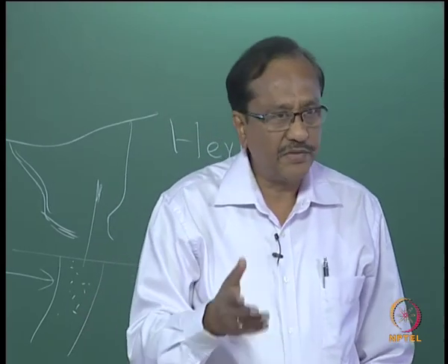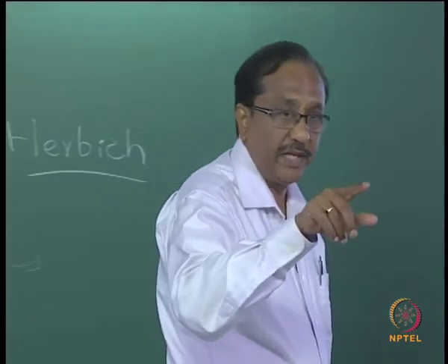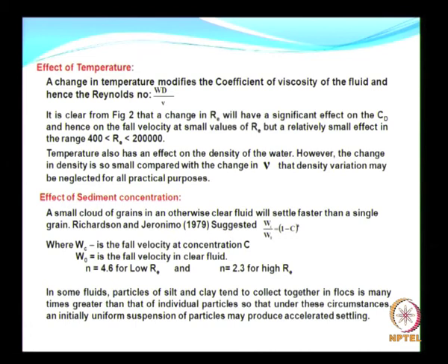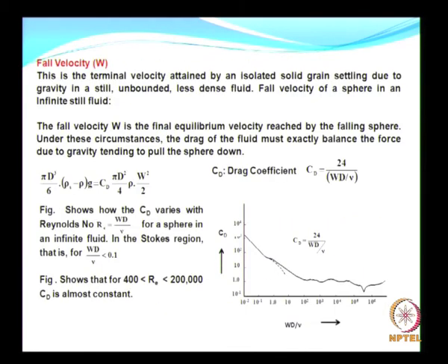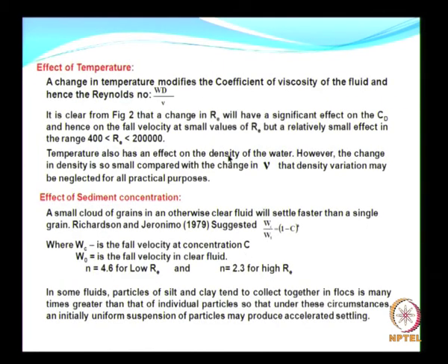The coefficient of drag is dependent on the Reynolds number, and the Reynolds number has the kinematic viscosity, which is a function of temperature, and that is where the effect of temperature comes into the picture. Earlier, in the picture of the variation of the coefficient of drag, you see that the Reynolds number has a significant effect on CD, at least for a smaller range of Reynolds number.